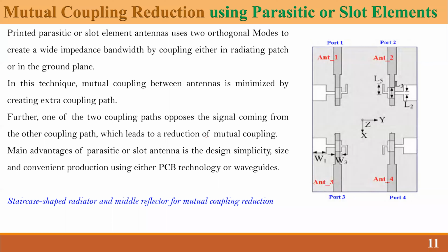One more time. Now you can see that this antenna is radiating something like this, and this is giving you some mutual coupling. In this particular case, it is mainly reduced due to the asymmetrical structures. Okay, and the radiation pattern will automatically be improved, or the mutual coupling will be reduced, due to this decoupling method. So this is one of the ways the parasitic slots will help you.